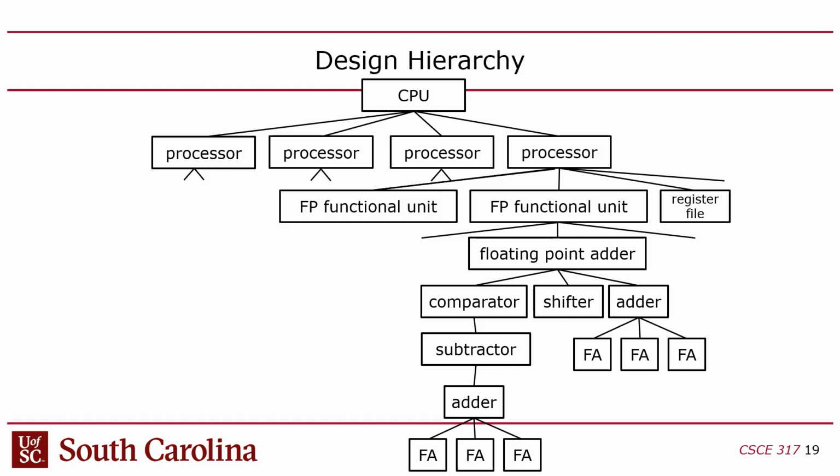Now you might then say, well, wait a second. If you've got a processor that can run pretty much any Turing complete program, in other words, anything a computer can solve, the Nios can solve it. Why do we need to design any more hardware? Like why don't we just say game over? You know, we're done with hardware design. The reason is because software is also very slow compared to hardware, and most importantly, it's non-deterministic.